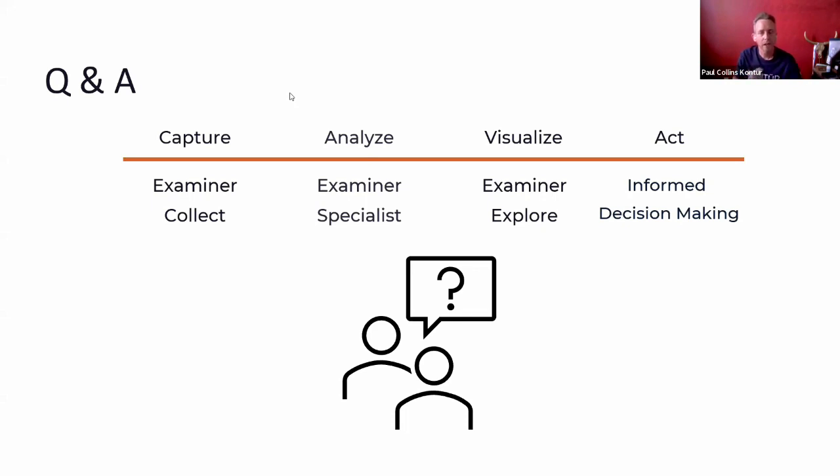How would you approach an area where no reliable GNSS signal is available? How would the solution support that? Where there's no reliable GNSS signal at all? Well, lots of the times, if you're inside and had no GNSS available from the very beginning, we can use a total station if you need to do that. Of course, it's much slower. You can create base stations. That's no problem as well.